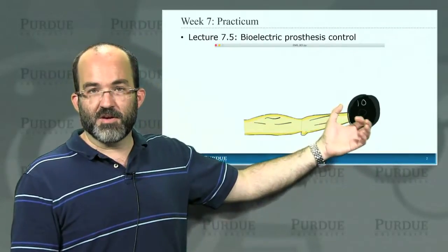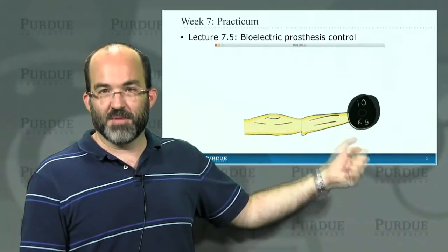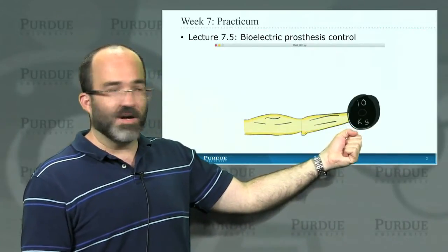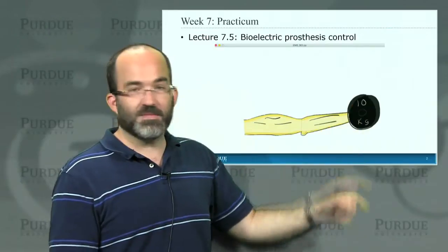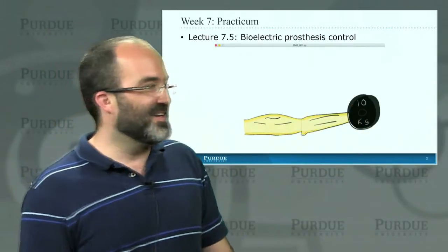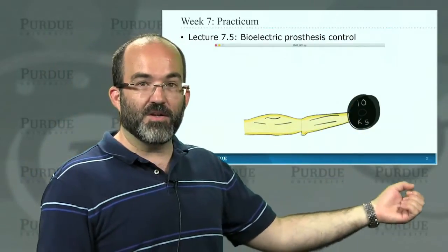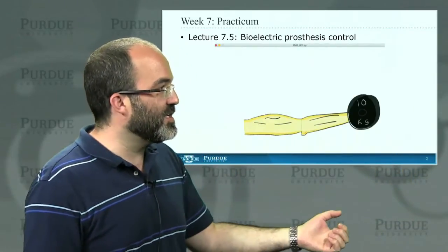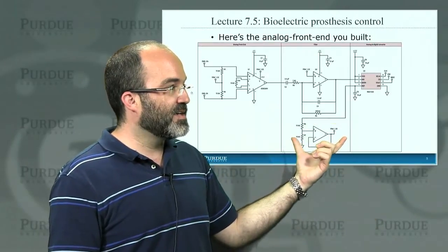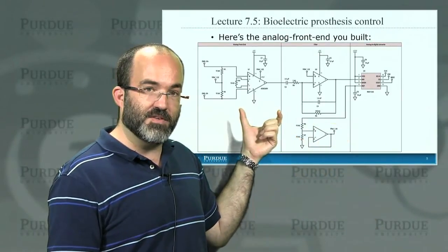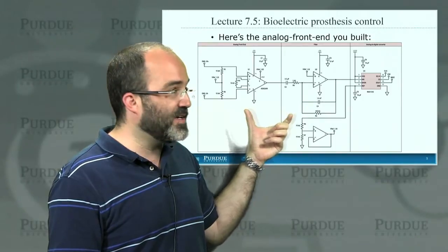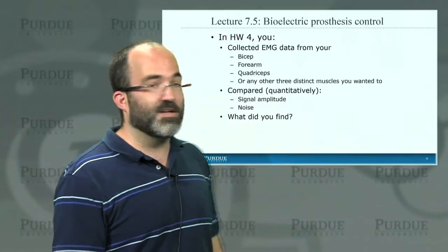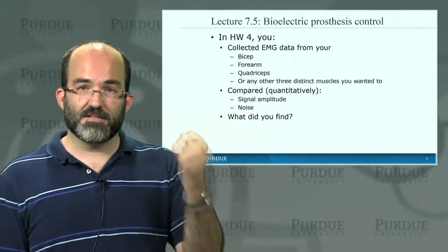We are engineers. We are not artists, so the graphic is limited by our artistic talent. But anyway, it's a drawing that we made of an arm holding a weight in kilograms because we're engineers and we don't use pounds. When you use your EMG incoming data stream, you're going to need to find a way to take this graphic and, taking the electrical activity you recorded with the analog front end with the amplifier that you filtered, that you digitized, and then you transmitted with the Raspberry Pi, make that arm flex on your screen.